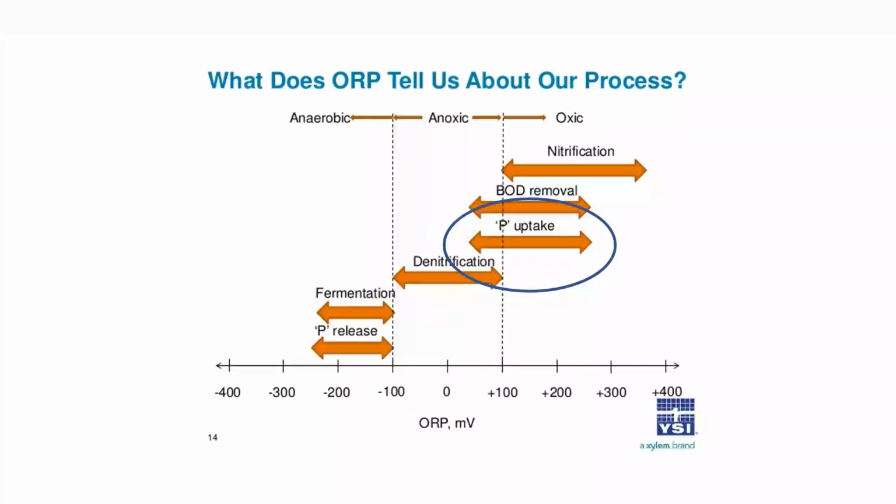So there's a possibility that you can get good ammonia removal, because ammonia removal actually not only does not require BOD removal, but it kicks in after the BOD removal is well on its way. So you need a slightly higher pH than you have for ammonia removal. And in summer months, if all the conditions look good, but you're not getting the good phosphorus uptake in aeration, it could be you need to slip some BOD into the aeration. And we'll talk about strategies for that.